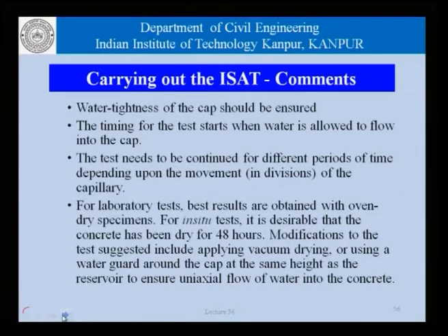For laboratory tests, the best results are obtained using oven dried specimens. For in situ tests, it is desirable that the concrete has been dry for 48 hours, and modifications to the test suggested include applying some kind of vacuum drying on the surface or using a water guard around the cap at the same height to ensure uniaxial flow of water into the concrete.